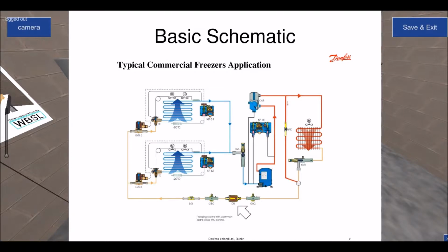In other words, what we also have to be aware of is that regulation, i.e. the F-gas regulation, makes it illegal for any refrigerant to be deliberately vented off to atmosphere. So we must take every reasonable and commercially viable step as refrigeration engineers to ensure that the refrigerant stays within the system, or stays within sealed systems, and does not exit the systems and enter the atmosphere.